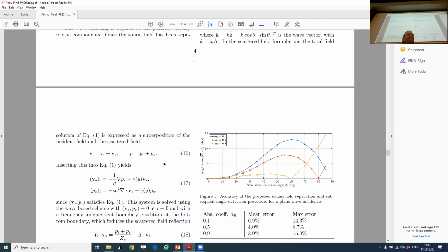We thought about it, but when you have many waves impinging at the same time, you have the boundary, and you have some points in the boundary of the mesh. I have many waves coming in at the same time, but I can only select one boundary condition here. So even if I could detect some advanced direction of arrival things to detect 3 incidence angles at the same time, I couldn't really use that information because I can only select one boundary condition.